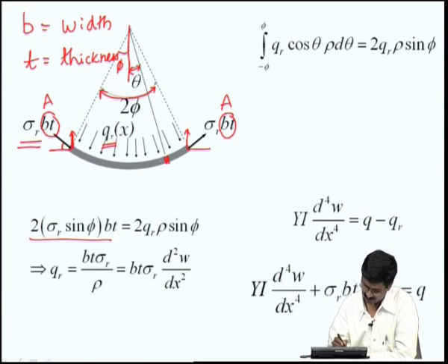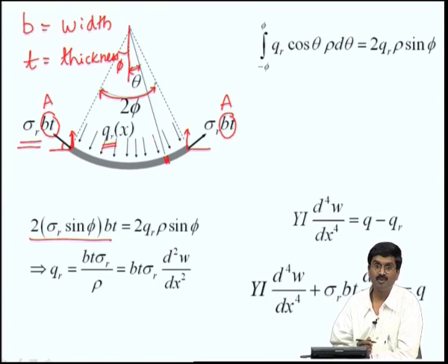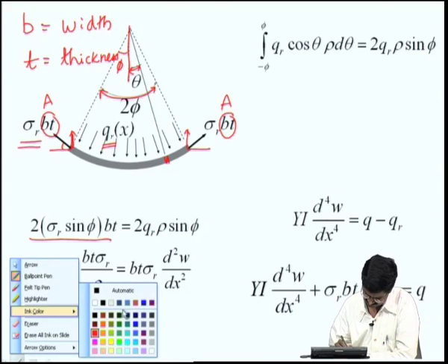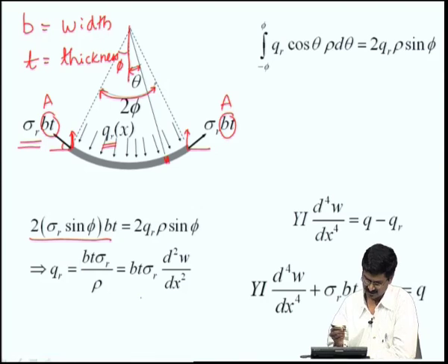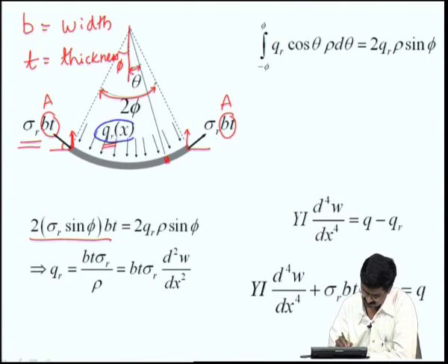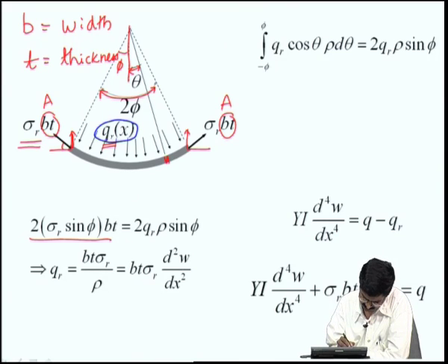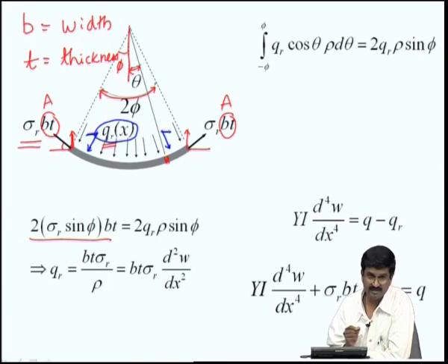Okay. Now, what about how is that compensated? And that is compensated with the QR, that is a transverse loading. So, let us use a different color to make that. So, now we want to see the effect of this QR, when I take a force over here and a corresponding force by the same angle over here, there also the horizontal components get cancelled, one goes that way, other goes this way, they get cancelled, only the vertical components will be there.